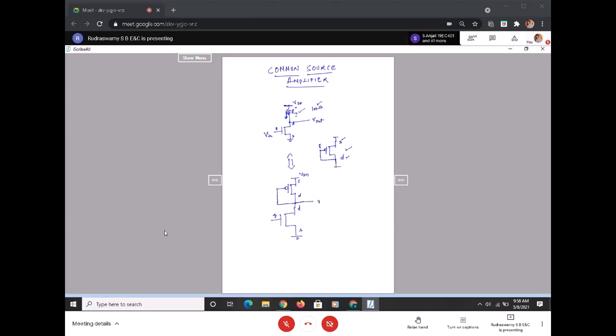And now can anyone tell me when exactly I can replace this PMOS transistor, which is a kind of diode, in place of the RD? Under what condition of this transistor? Or when I can say this RD and this PMOS transistor, where the gate is connected to the drain, or shorted, is equivalent? When it passes constant current, sir.